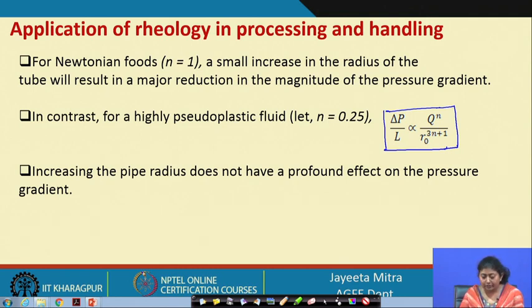All these are very related. So, if you change one dimension, consequently your other dimension will vary significantly, and that also varies for different fluids. You can't take the same geometry and same pressure drop for two different fluids whose rheological behavior is totally different. So, you have to design each and every section specifically for each kind of fluid.